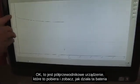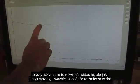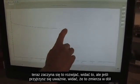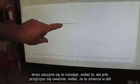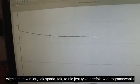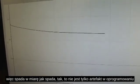And see how this battery under this 1 amp load is sort of now finding a level. See it? But if you look very closely, it's stepping downwards. See it? So it's stepping down as it goes down. Yeah. That's not just an artifact in a software program.